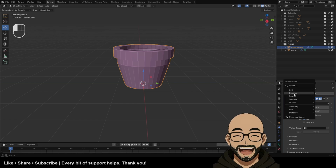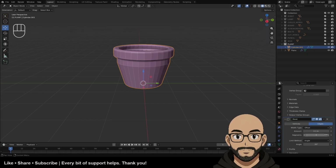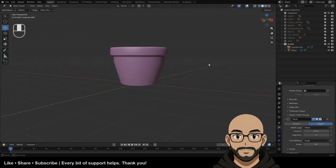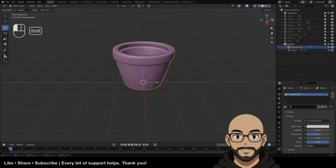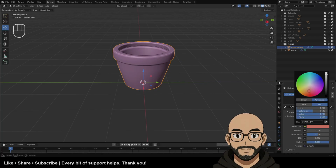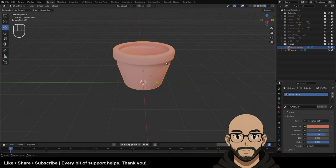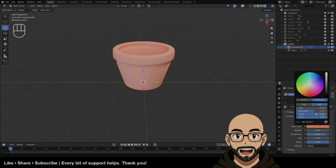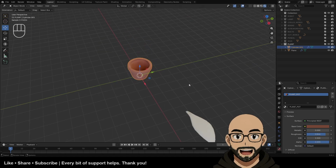plant pot, add a bevel on that. Shade auto smooth. Give it a material. Plant pot. And I go for kind of like a clay material. This is going to be rough. Let's just maybe a little bit darker. That kind of gives you that clay pot idea.